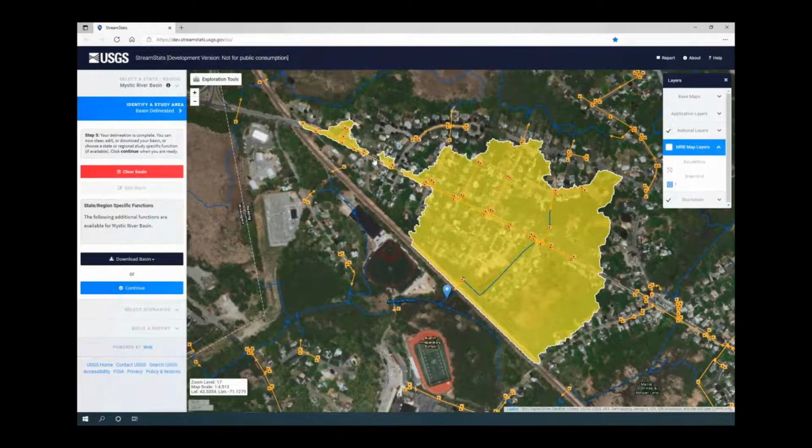So this area actually contributes to other areas. I'm thinking this flow, this culvert that goes under the railroad here, is probably the contributing area for this stretch of this neighborhood. And again, another point here, that's a disconnect. So these are the types of unique delineations that you see with urban storm drain delineations.